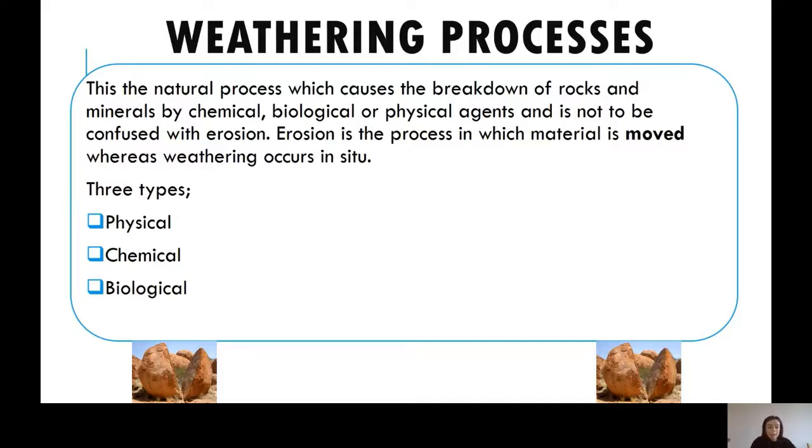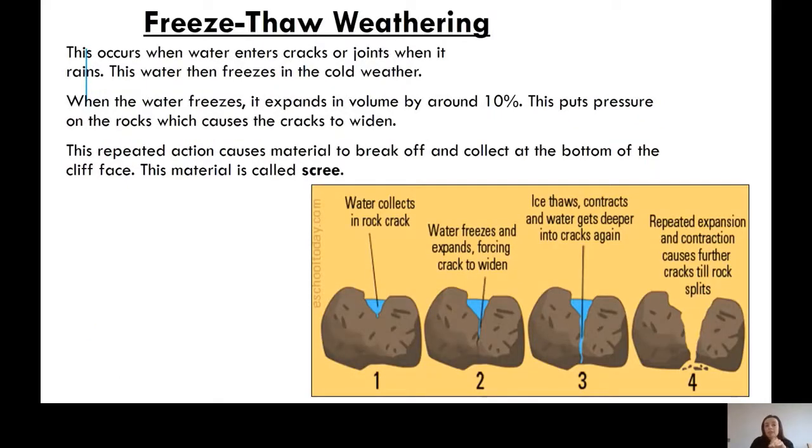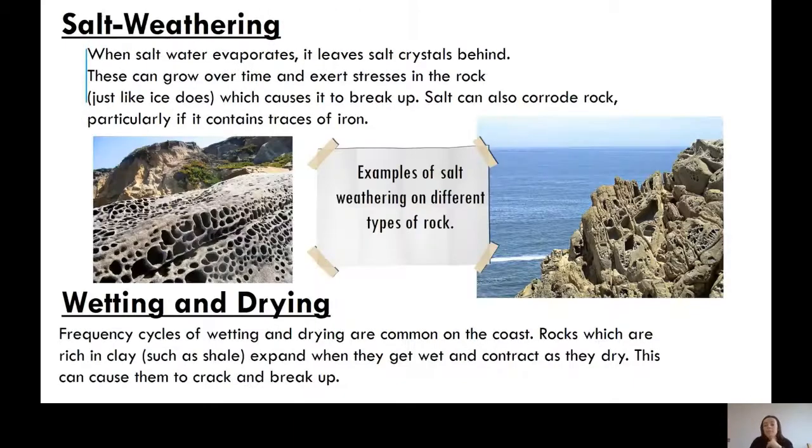I don't have time to go through all these now, but a physical example of weathering is freeze thaw. You also have salt weathering, where seawater is sprayed onto rocks and leaves salt crystals behind, and these exert stress on the rock. You have wetting and drying, where porous rock will absorb water and expand, and then dry out, and this wetting and drying will cause cracks. That happens in shale.